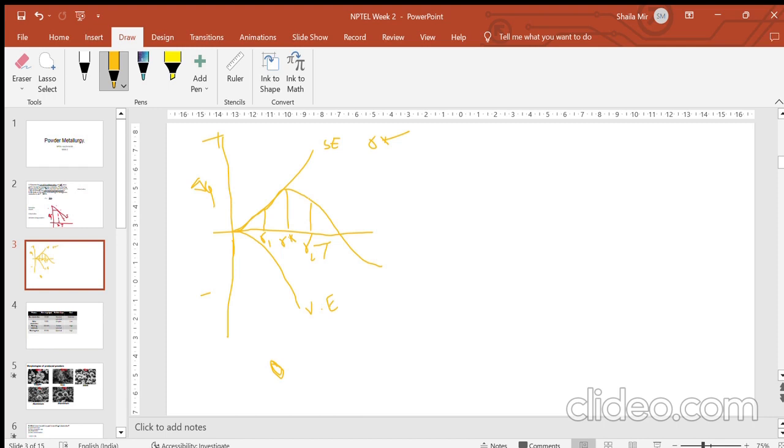And for that, it will lose its energy and it will try to agglomerate with one another. It will try to coalesce. So these are the two particle radiuses. If it is less than R1, then it will not be sufficient enough to be nucleated from the liquid. If it is greater than R star, the critical radius, it will try to grow into a bigger nucleus, right?